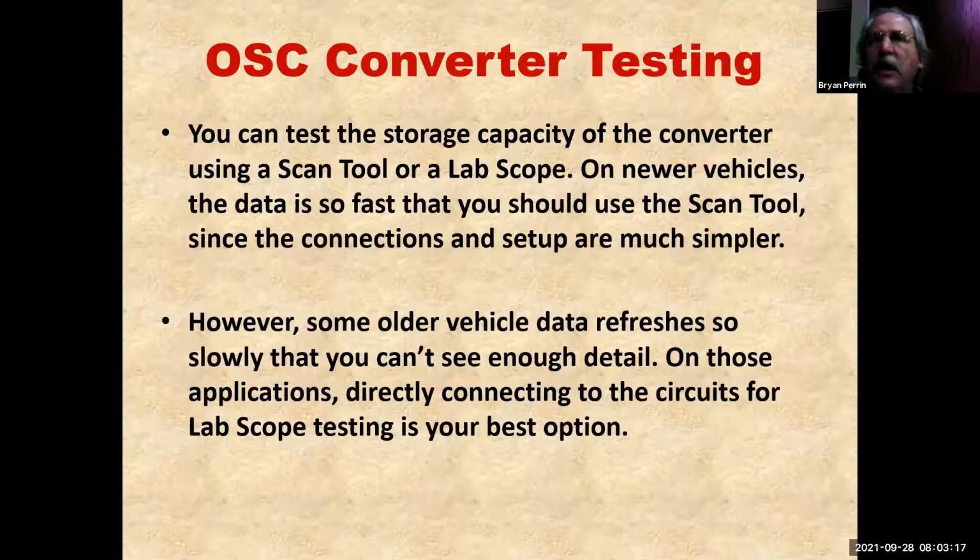It's that slight, but that's what's causing the code. So sometimes you really have to just go, wait a minute, I proved the converter has stuff in it, but yet I'm getting the code and my rear sensor stays low too much. The only thing that makes sense is an exhaust leak. So I really need to test and find that, and not just go, I don't hear anything. Hopefully at this point you understand that not hearing an exhaust leak doesn't mean we don't have an exhaust leak.